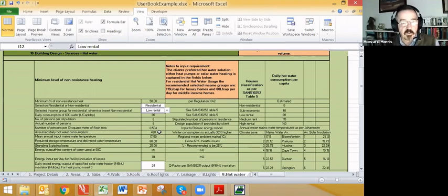Now, in order for the solar water heater to be meeting the 50% minimum non-resistance heating requirement of regulation XA2, and if you can see my cursor circling that important bit of legislation, or rather regulation, the sizing of our geyser is paramount.